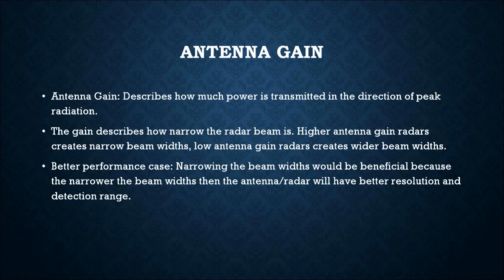So if you were to ask yourself as an engineer, what would be the best performance case that you would want your radar or antenna to perform, you would really want to narrow the beamwidths, and that is pretty much beneficial for us as engineers, because if we narrow the beamwidths, then your antenna and radar are going to have better range resolution, and you're also going to have better detection range.